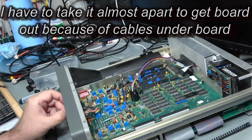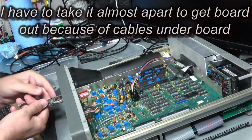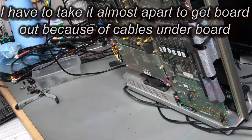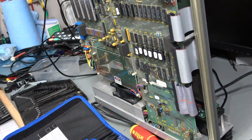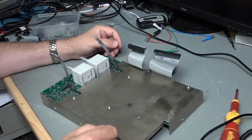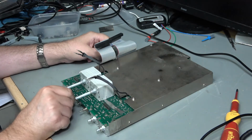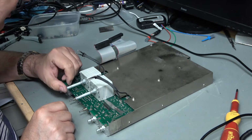So the pot is mounted on the top board and should theoretically be easy to get at, but I've looked at taking the bottom board out just to get access. Can't do that, so I'm having to take apart the whole thing pretty much, because on the bottom of the board are further connectors going through to the front panel, and I just can't get at those to reassemble it when the time comes. So all has to be taken apart just to get at one pot. Now all I've got to do is get the right pot off, the one that just goes around endlessly. I can just get in there.